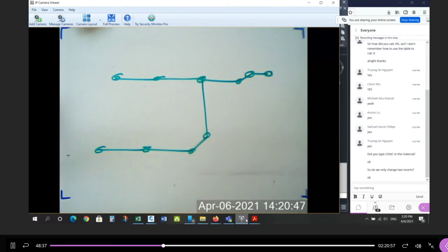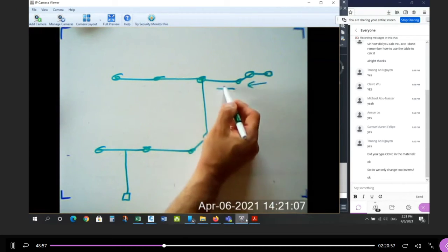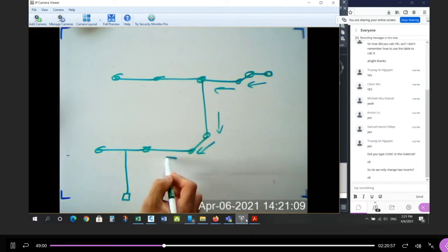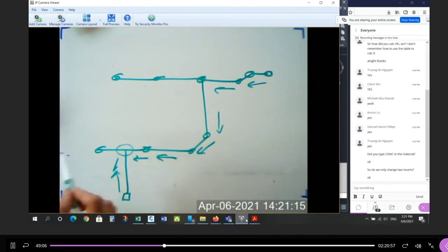Okay. Then we come back and we can find out what those sizes are when they're all 0.5%. We can get our design sheet ready. We can draft all these pipes in the profile view. Then we start from the bottom and work our way up. Then we stop that design and we start at the back with the catch basin and come down, right? So we designed going uphill. And then we start at the backyard and we design going downhill, and then we check what's happening at these points here.